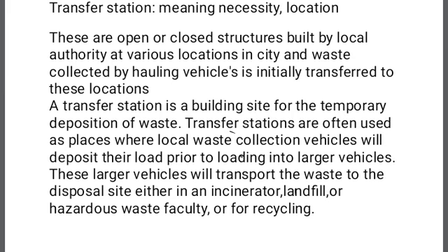Now, transfer stations are made of masonry structure or bedding, and sometimes a container is used as a transfer station. A transfer station is either a metallic container or a masonry bin, sometimes used instead of an open place, bedding, etc. The size of the transfer station depends on the quantity of municipal solid waste to be received.